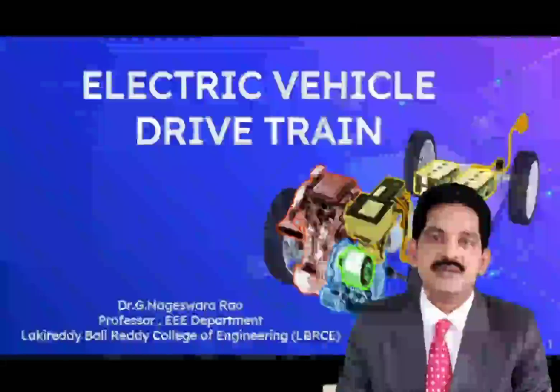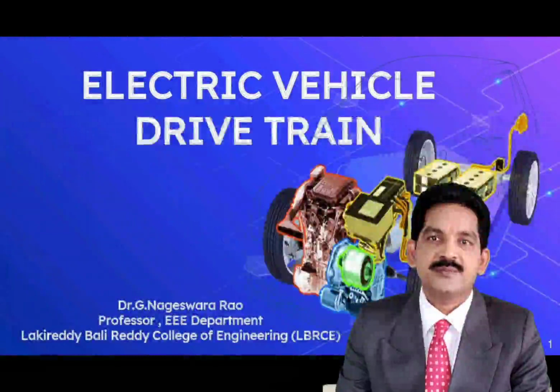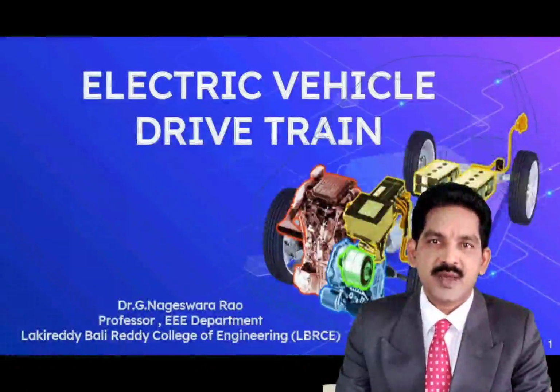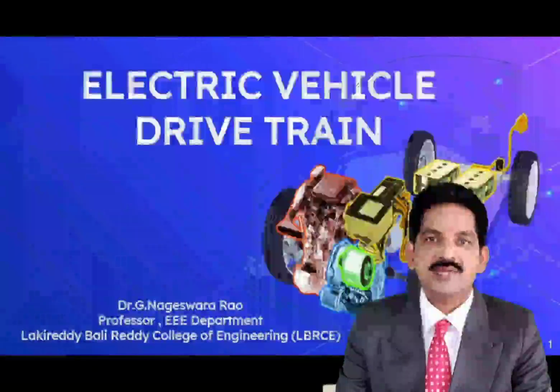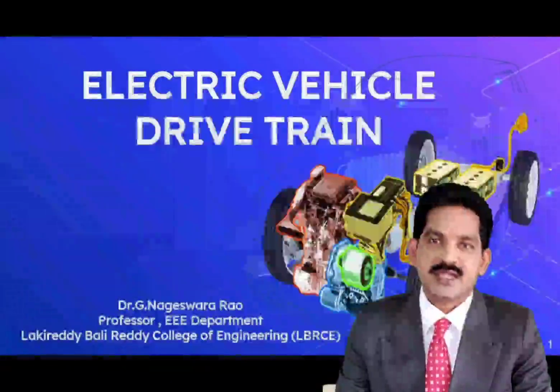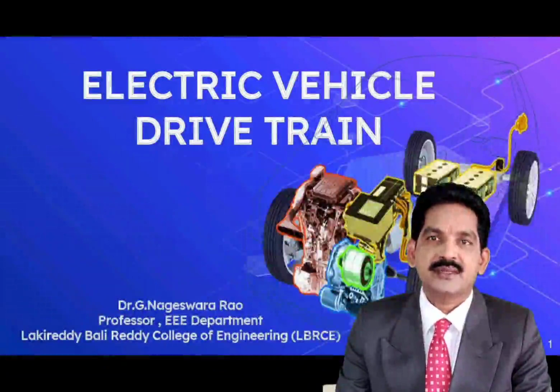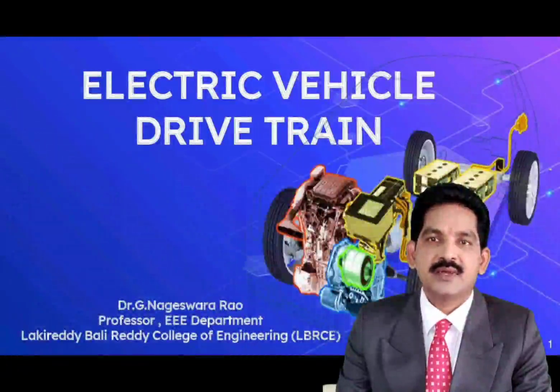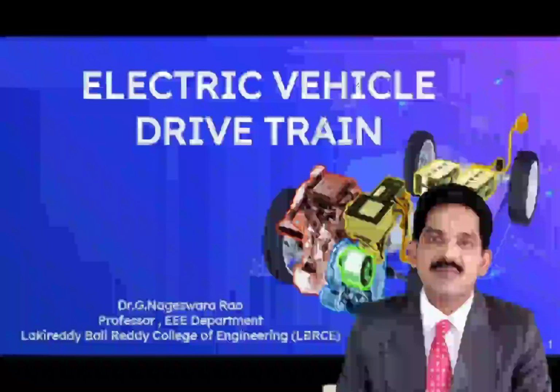A fuel cell vehicle may have a hybrid powertrain in which the fuel cell is sized at less than the vehicle's peak power requirement, and additional power is supplied from an electricity storage device such as a high power battery or ultracapacitor. Although a hybrid powertrain is more complex than one using a fuel cell alone, it offers advantages of regenerative braking, which helps vehicle efficiency, and the availability of greater power for startup and auxiliary loads.